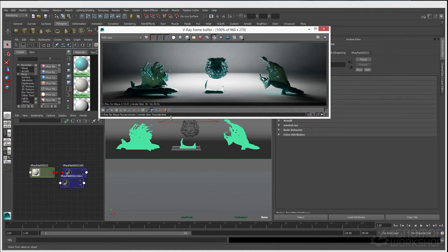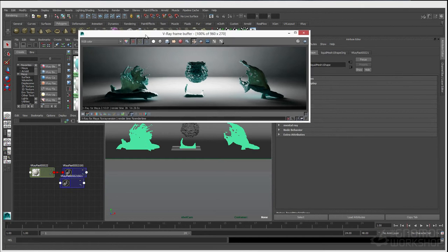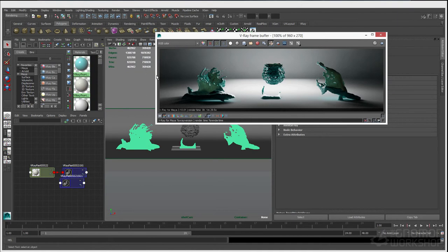because it can store instance data and also other kinds of information that come from other packages like Houdini or Softimage or 3D Studio, taking advantage of the Alembic format. You may remember this scene was something that we were using in the subsurface scattering demo. I opened it up because it has some really dense meshes inside. You can see right now my total face count is 900,000. And I just wanted to have something pretty dense just to really show the power of these V-Ray proxies.